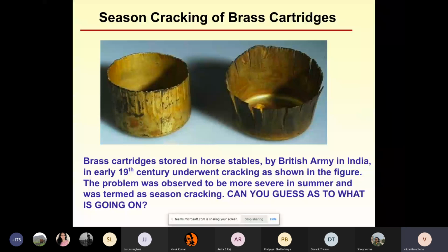Its critical stress intensity factor goes down, and as it goes down, at some point the residual stresses are strong enough to crack open wherever you have large stress and some earlier defects. And particularly this wrinkling was creating the stress intensity factors, and at those points it would start to crack open.